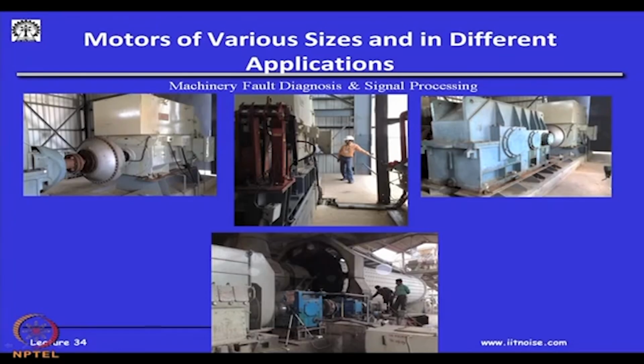Okay. And you will see these machines are maintained. The alignment has to be perfect. Otherwise, if there is a misalignment, again the rotor at one end of the motor is going to have an excessive force, and the bearing at one end may get damaged.